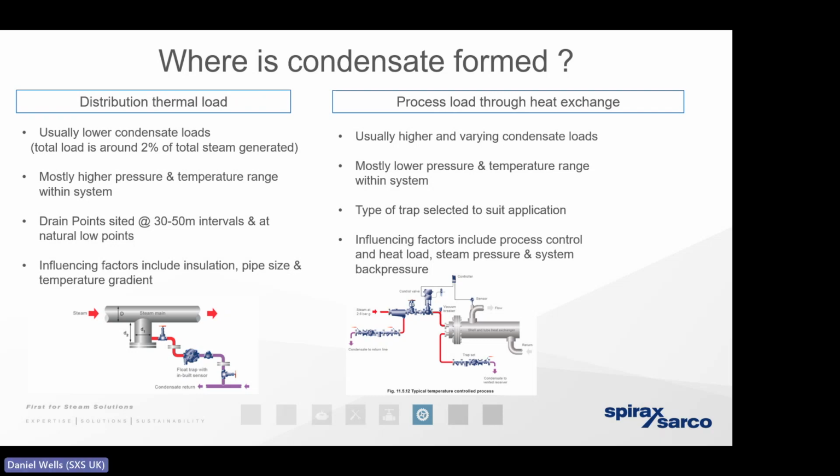And the running load assumes that the infrastructure is nice and hot 24/7, which of course it rarely is. We're going to find steam boilers switched off periodically. We're going to find different buildings isolated from time to time. And when those boilers are switched on, and when those isolation valves are opened, then a lot of the steam in the infrastructure is going to give up its energy to the pipework before it even gets to the process.